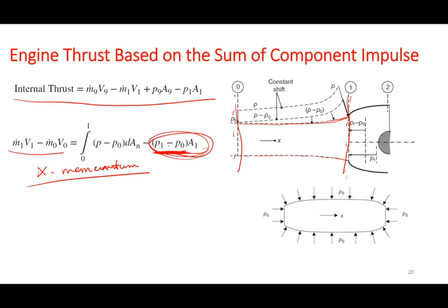And we also have this area change, which has a pressure distribution by itself, right? At each point, we have a pressure P. We can call it P of X, whatever. Here we have called it P. And then to find that force, you essentially have to take the integral of the pressure distribution here with respect to the changes in area, the respective area.